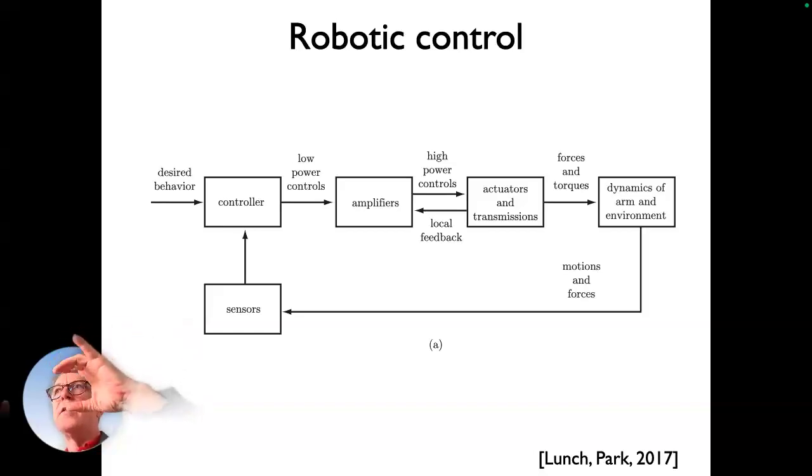And the fact that we have this very good loop means that we can give electrical signals to the motors that already have some mechanical meaning. That's an achievement. If you just take an electrical motor as such, that wouldn't be the case. The same voltage you send to the motor would have quite different effects depending on how much resistance there is, for instance. But this really makes robotic control much easier these days.